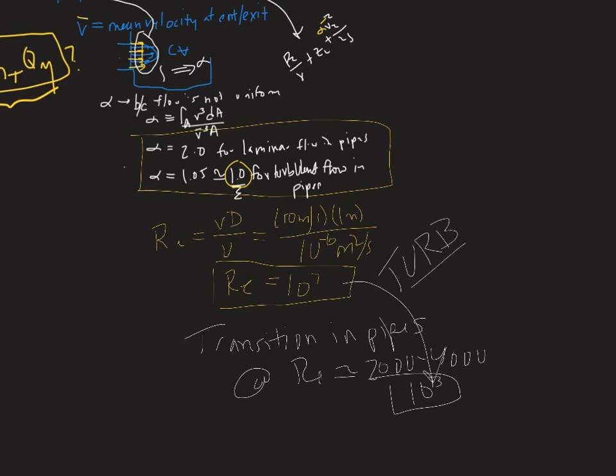Which is good. I think this hopefully can show you why, usually when calculating a Reynolds number, we just care about transitions. So 2 significant digits is all you ever need for this. Right now for transition, you probably only need 1, whether or not it's turbulent or laminar. But later on in the class, there will be a time when 2 significant digits will be useful, so usually we'll do 2. So in this case, I guess it's 1.0 times 10 to the 7th, if we want 2 significant digits.